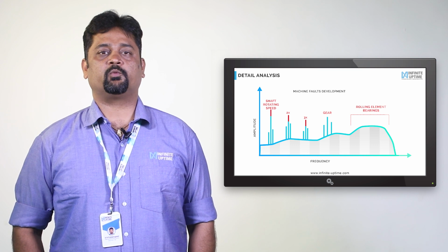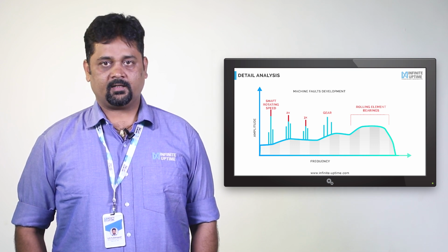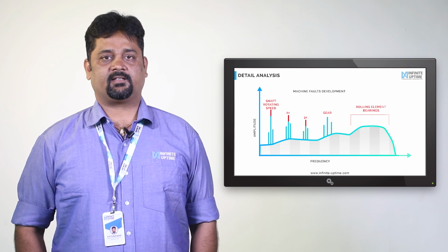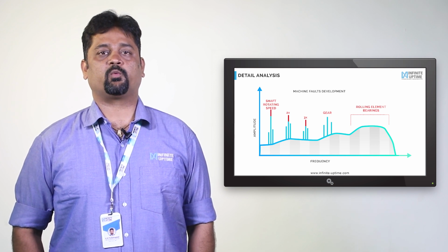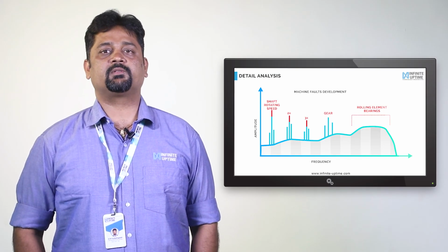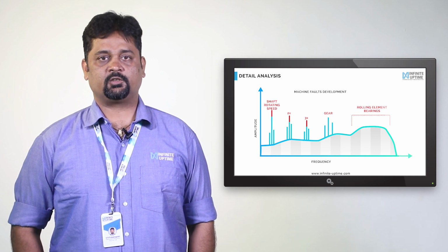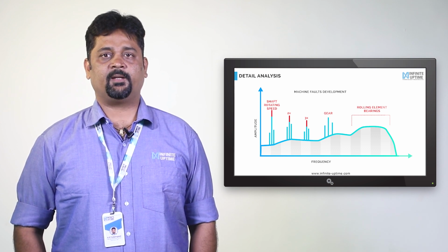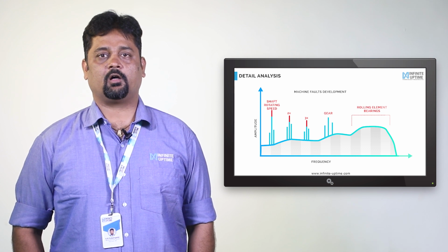Each fault in the machines will have different frequency patterns. For example, specific machine faults will generate 1x harmonics. Over a period, it will generate harmonics that are 2x or even 3x. Along with this, if the sensor is mounted on the gearbox, it will generate gear mesh frequency with its related faults along with harmonics. Bearing frequency issues also start from the high frequency band. All these problems can be well studied and analyzed through spectrum analysis. This helps any analyst to take the suitable decision on maintenance.